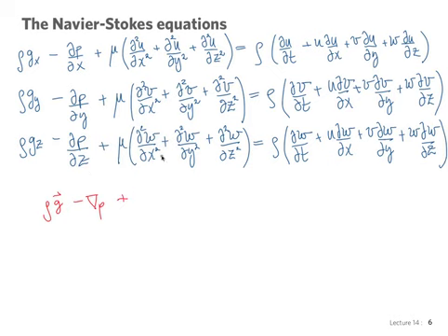And this is the differential operator we call the Laplacian, and we write nabla squared for the Laplacian, and I'm going to use v with a little arrow on top to indicate vector velocity equals rho, and we have the partial derivative of the velocity with respect to time plus just the same as in the Euler equation. This is basically the same acceleration term that appears in the Euler equation. What's changed is the forces.